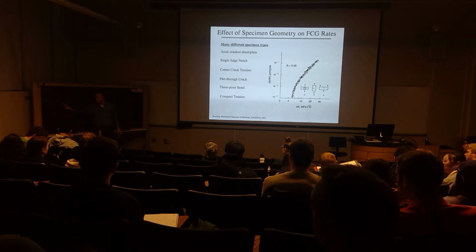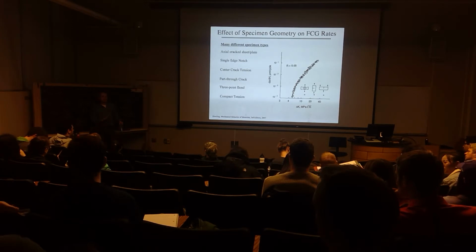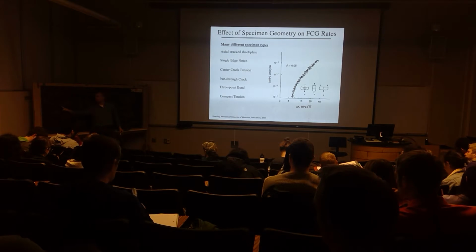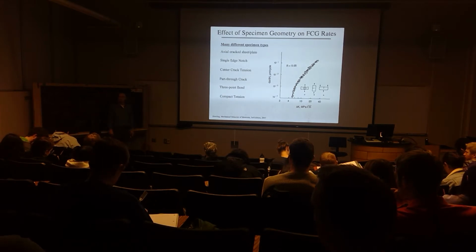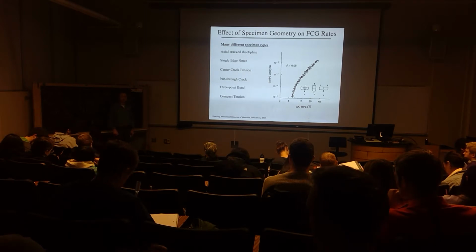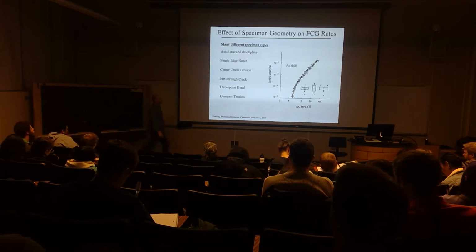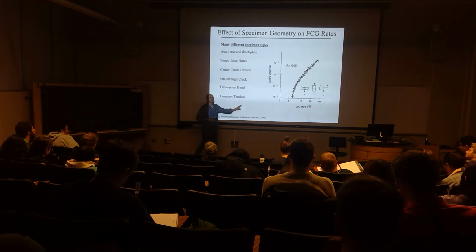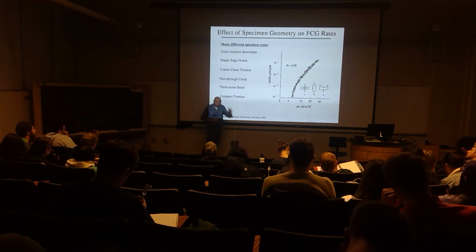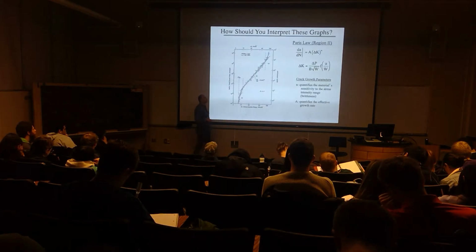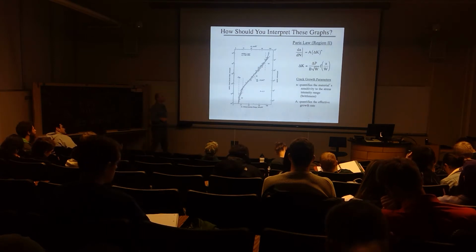The magnitude of the stress, the global stress, the nominal stress, the geometry factor, and the crack length at that position. So the geometry of the structure makes no difference, only that we know the stress, we know how to calculate the geometry factor, and we can accurately look and see or estimate what that crack is. All right? Fantastic. So this is maybe not that impressive, but really it is the door that opens up and says you can apply this to all of your materials. Okay?